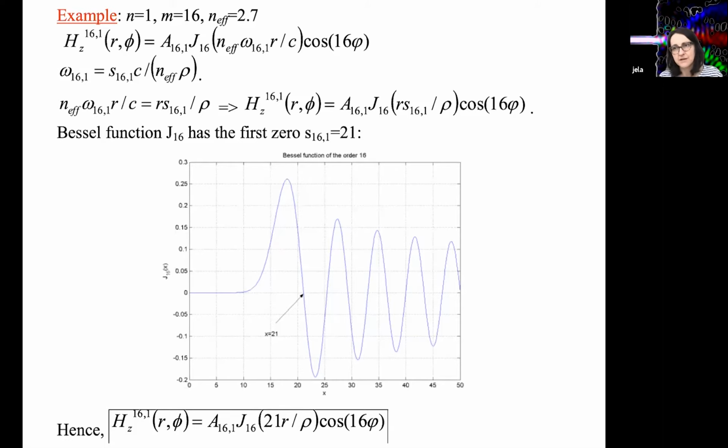Right? So that's another reason why you don't want to operate in those rings, in those higher order modes. And that's also the reason why we typically go to ring geometry instead of the disk geometry to fix that problem. So going back to our 16.1, TE16.1 mode, right?